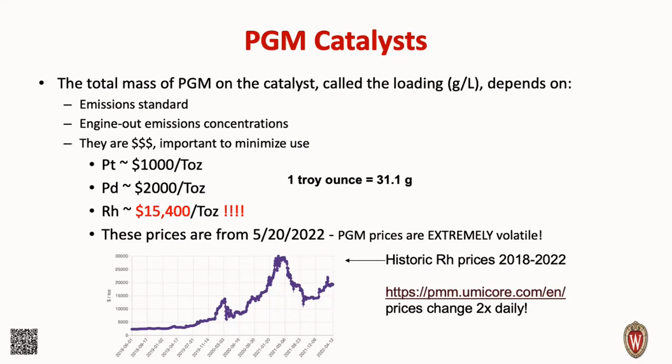If you're interested, vehicles that have a PZEV designation typically have the highest catalyst loadings on them, so those will tend to be very expensive, and that's why you see catalytic converter thefts on cars like Priuses, because they have so much catalytic loading. It's worth a lot of money.